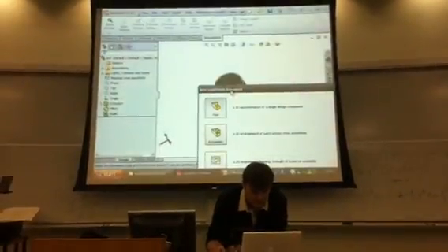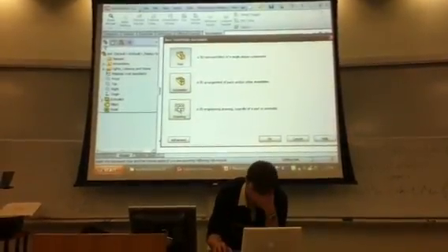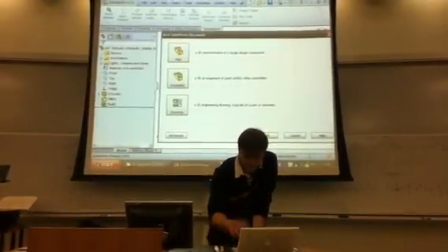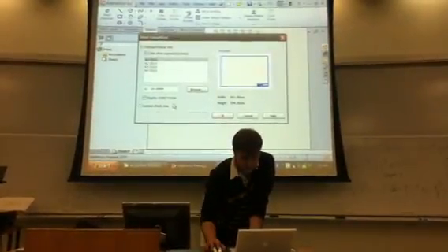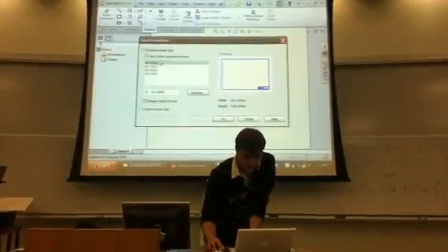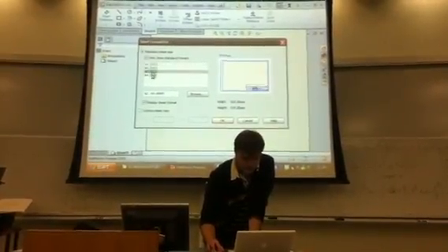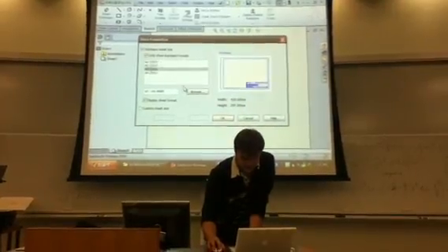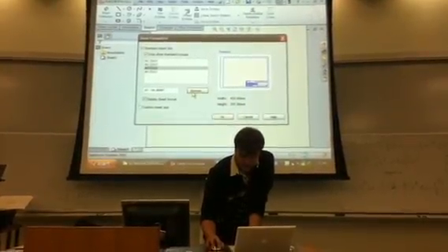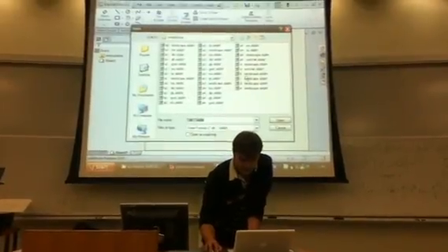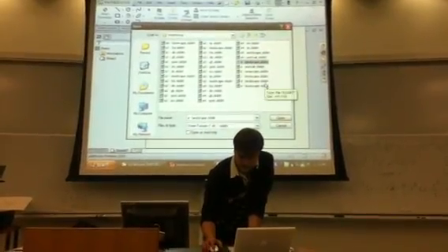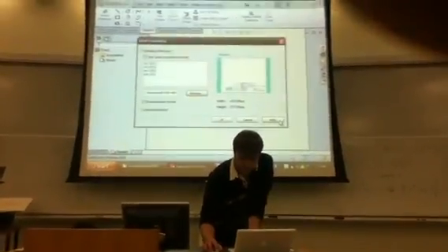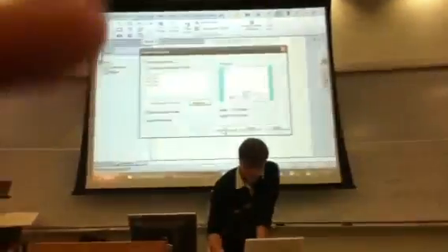Make a new file, and at the bottom here you can see we can make a drawing file. So double click that. When you're making a drawing file, they have different templates that you can put your drawing on. There's 4 standard ones here, but we're not going to use any of those. So hit the browse button. There's one that's called A-landscape. So open that and press OK.